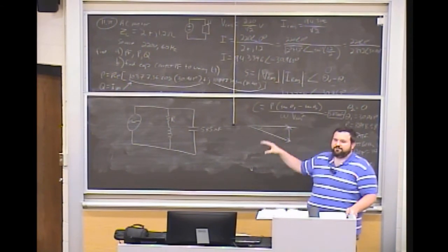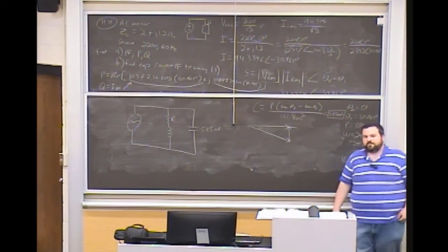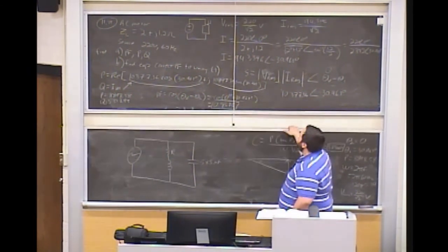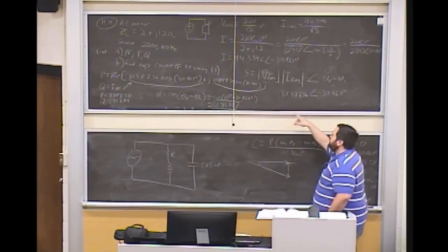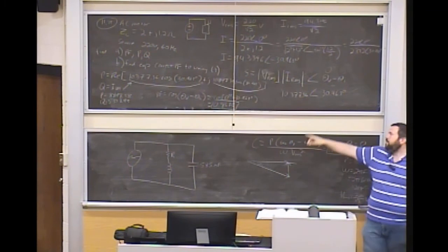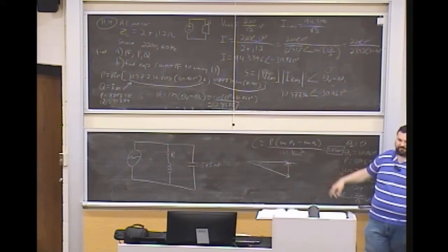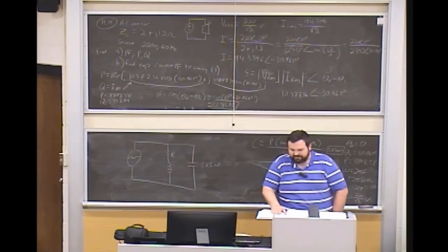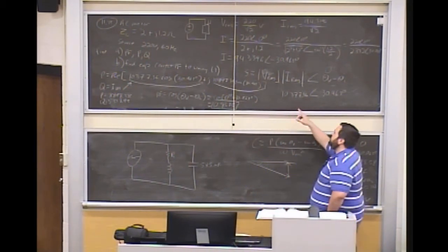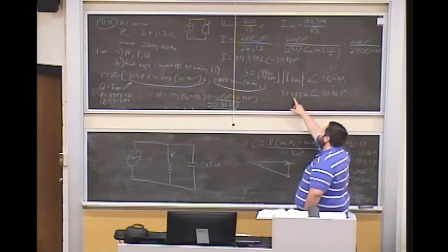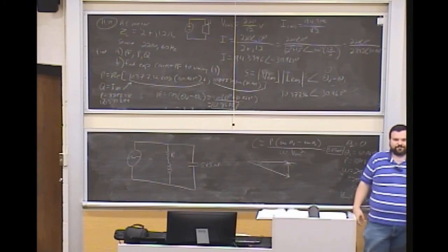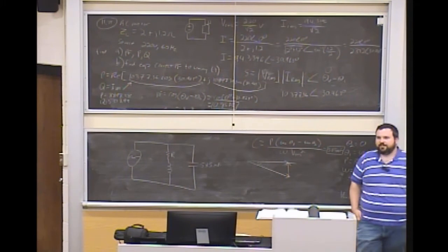That's just the magnitude of bolded S. So this S that we solved for here would be bolded. I don't have a bold chalk, but that would be your bolded S, and that is your complex power. If you want to get to the apparent power, it's just the magnitude of this. So you could go about just doing square roots of angles and such, real component, imaginary component, all that.